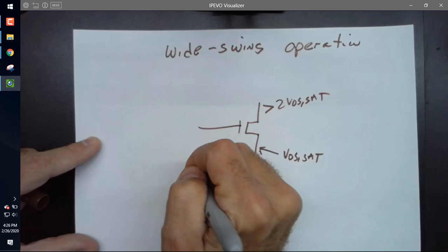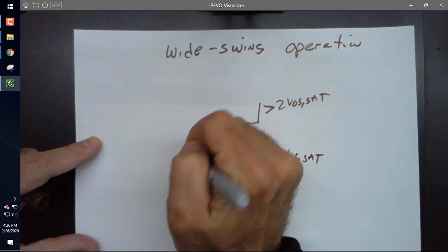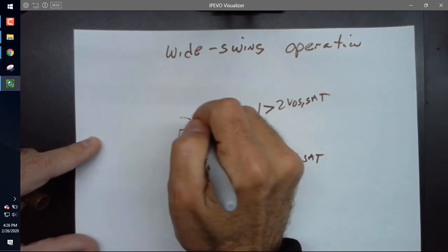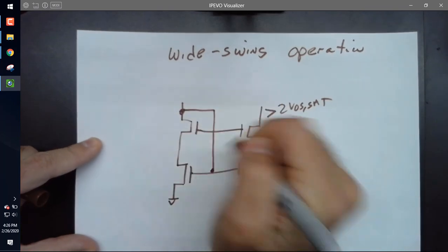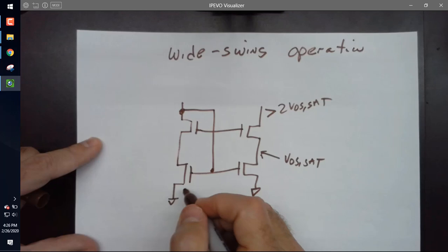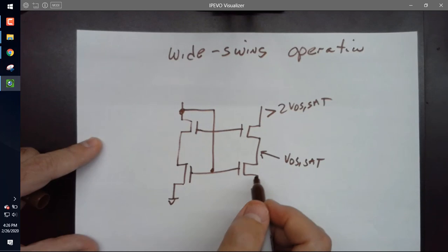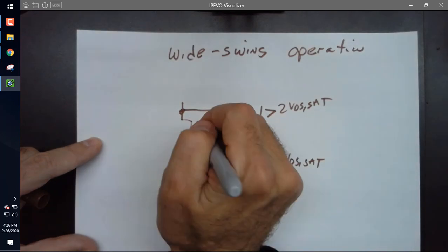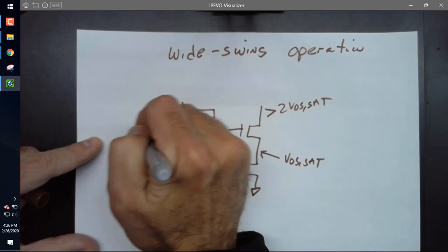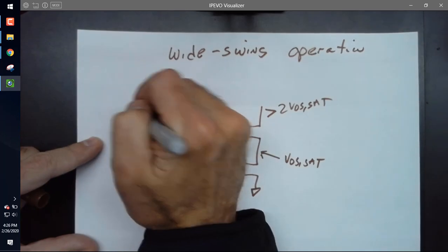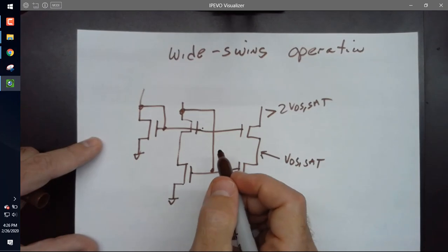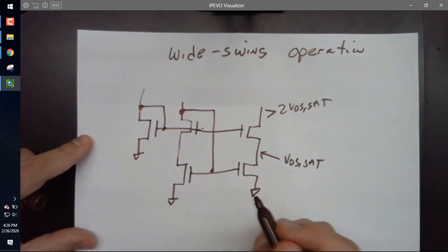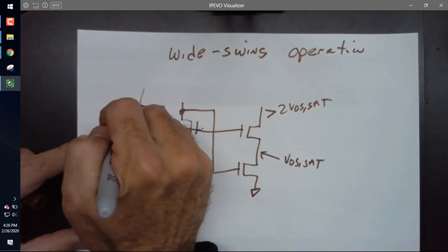And over here, I'm going to connect this up. And I connect this down here because, again, what does the VGS? The VGS is set here by, that sets the current mirror, right? And then over here, I'm going to come in and I'm going to set this device to have what? We just saw it on the slide. 1/4, right?